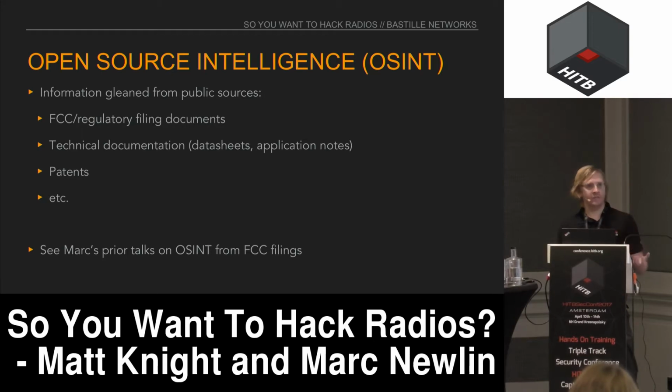In the US, we have the FCC, IC in Canada, CE here in Europe, and each organization has the same purpose of evaluating a device to determine: does it fit certain constraints for that certain market? So that would be what frequency does it operate on, what is the transmit power, the channel bandwidth, does it hop around, what is the duty cycle. And the purpose is to, again, meet these regulatory constraints.